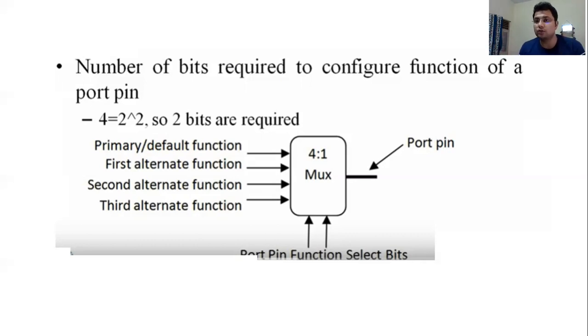Out of that 4 GB, somewhere these registers will be located, and those memory locations are fixed. So the system can understand if we are using the pin select 0 register, pin select 1 register, pin select 2 register. In total 10 pin select registers are there. Later on we will come to a conclusion on why 10, 11 pin select registers are there.